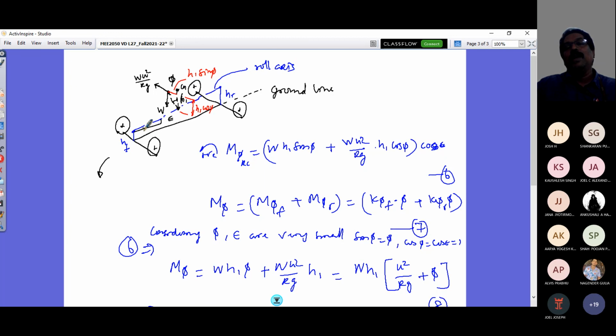Or if you want to have your roll more on the rear, you go a similar way. Put your roll stabilizer on the rear side, and you get more stiffness there. So the roll moment distribution is smaller compared to that of the front, and that can take you to oversteer. So the auxiliary stabilizers, or roll stabilizers, are an addition to the suspension in vehicle design that you can see. So with that note, I stop today's class.